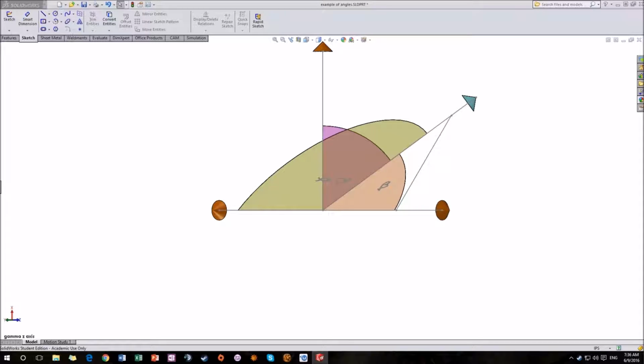Now we're going to look at the z component. Like we did last time, we're going to go ahead and disable all these other coordinate direction angles. And similarly to last time, we're going to draw a line that connects our force to our z-axis. As we can see, we make another right triangle between the z-axis and the force, and all we need to do is take the cosine of the angle gamma and we will get the z component.